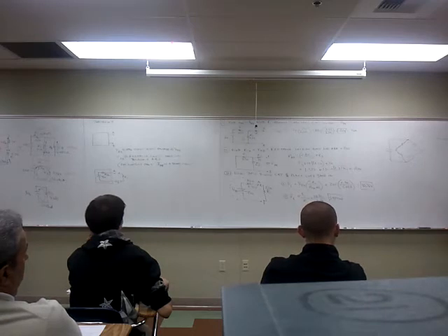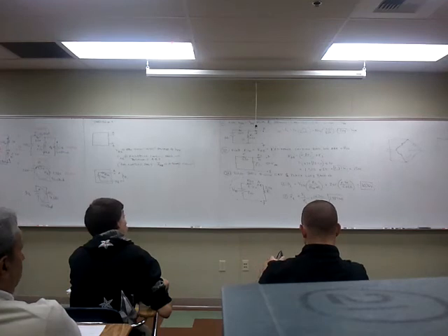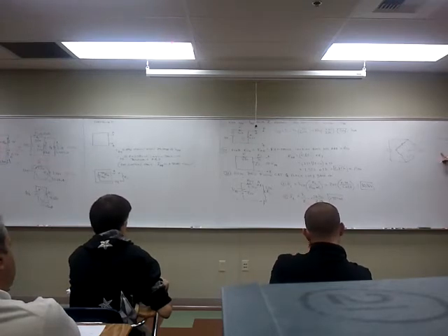And an offshoot of this theorem is called Norton's theorem. Norton's theorem makes this circuit a snap. Short circuit here, and look at this. When we do Norton's, would any current flow over here from this power supply? No, it's shorted right there. All this falls away. You do 1 Ohm's law calculation.